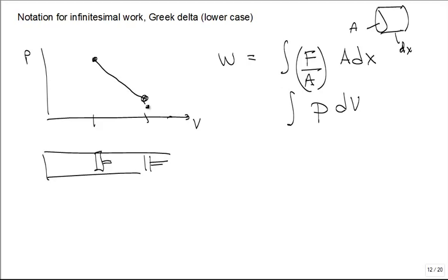Now, when you were in Cal 1, they really didn't show you any graphical means to integrate things, did they? Or maybe they did. But visibly, if this is zero pressure, and the pressure is going up from there, what does the area under the curve visually represent? The work. That integral is the area under the curve, as long as you're going in that direction. If you go the other direction, it's a negative of it.